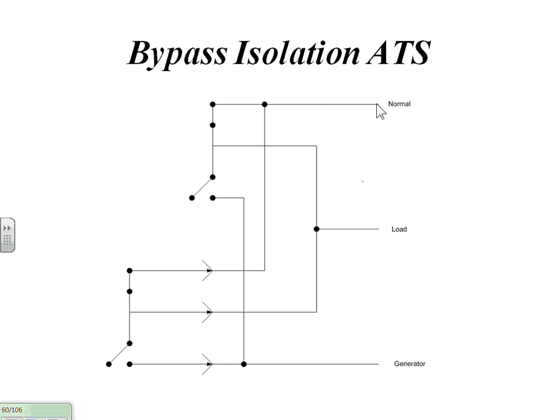Okay, normal, and since this is the rack out portion, the switch on the bottom is actually the automatic transfer switch. So normal power will come in here, through the switch, through the normal contacts, and out to the load this way. So all is good.